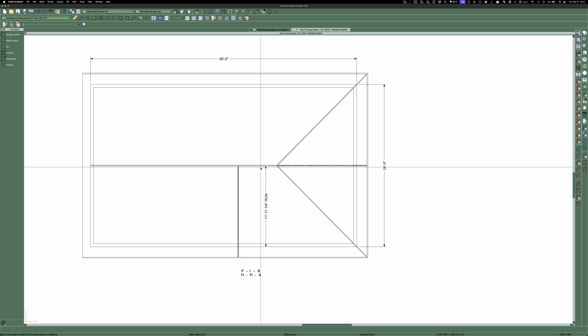No, it's not that heavy. It is important, but if there was a slab on the ground, you could point load, and maybe if there was an opening here, you could put a header across and bring that load down and just sit on concrete, because we do that all the time in Texas in the South. Unless you're going to have like a 50-pound snow load, that might be a problem. But there's other ways around that too. You can put beams up in the ceiling. There's all kinds of ways you can mitigate load, get it out to the outside walls where they're designed to hold all that weight. But anyways, I'm getting out of whack here.